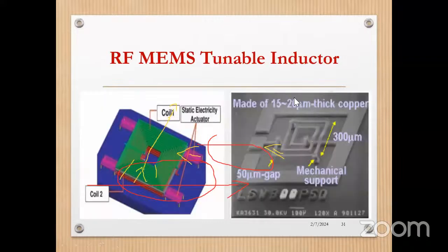And the next one is a very important application, that is the tunable inductor. For a tunable inductor, we can see that the inductor will be in coil shape. So if it is a round coil, the size of the component placed above the PCB, the thickness of the PCB or the component, will increase. So I have to find an alternate method so that this inductor is placed on a planar surface. Planar surface means it should not be like a round coil.